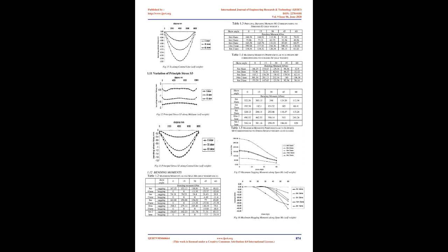2. For the single lane bridge only the 8 m span was taken and 5 different skew angles, 0 degrees, 15 degrees, 30 degrees, 45 degrees, and 60 degrees, were considered. Hence 5 different models were considered for single lane bridges. The width of the bridges was taken as 5 meters including curbs of 0.225 m width and 0.225 m depth provided on both sides. The depth of the slab was taken uniform at 0.750 m.